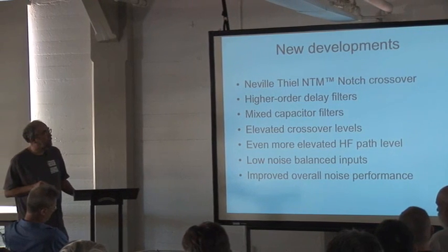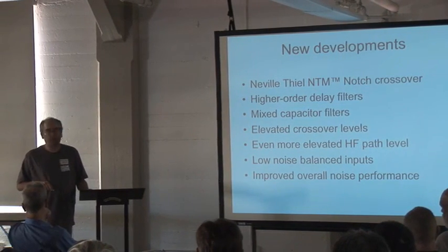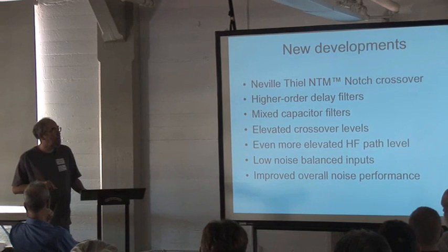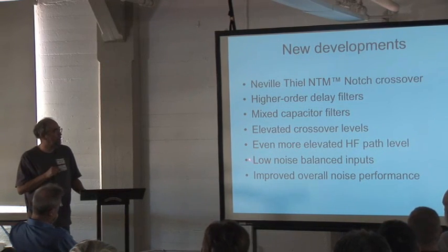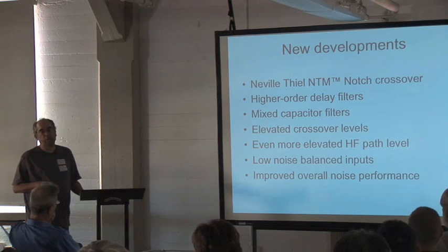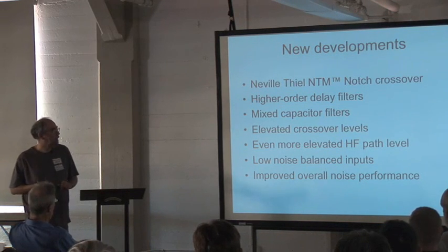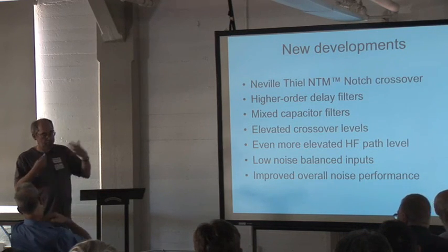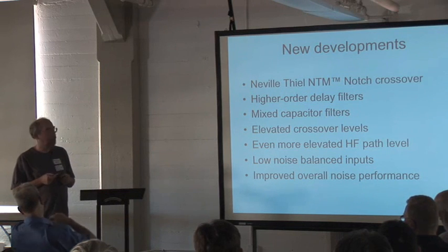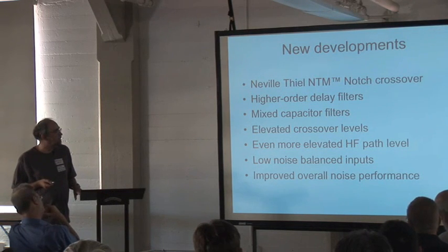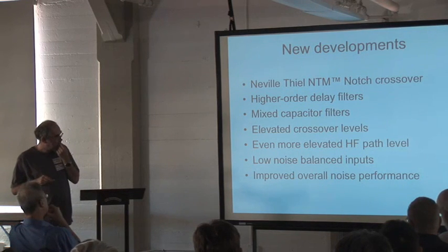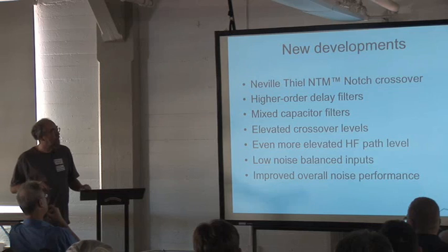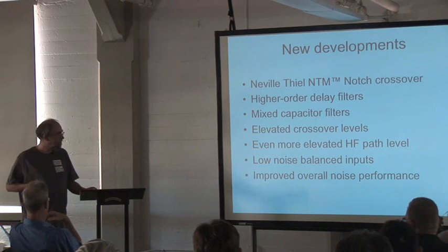And while you're worrying about noise in your crossover, one of the things that you find is that probably the noisiest part of it is the balanced input amplifier, which you might not expect. So that is one little bit of circuitry, which then splits into your 3 or 4 paths. If you can make an improvement to that little bit of circuitry, that ripples through the whole business, and the whole thing becomes that much quieter. So I'll be talking a little bit about that, and I'll demonstrate how much that improves the overall noise performance.